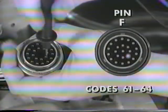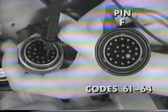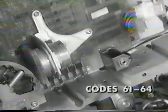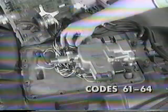Now, measure between F and vehicle electrical ground to make sure we don't have any shorts in the harness. The reading should be open or infinity. If it's not, there's a short to ground and you'll need to repair or replace the harness. If both readings are okay, replace the shift bar cover. Don't forget to reconnect all of the connectors, including the sensors and the auto shifter harness, and don't pinch the wires under the shift bar cover.